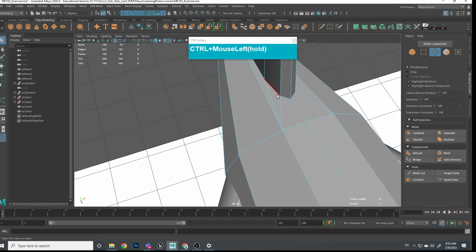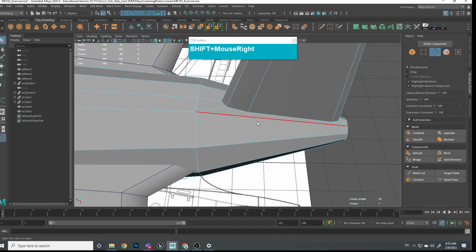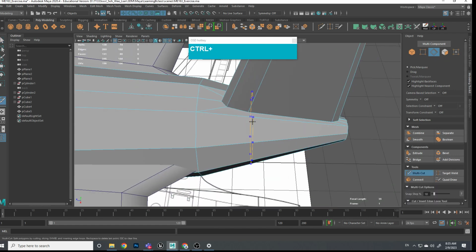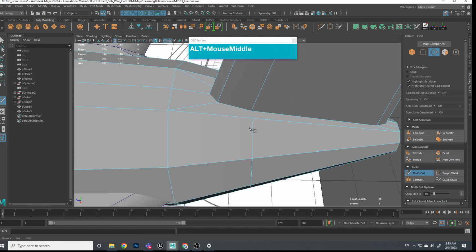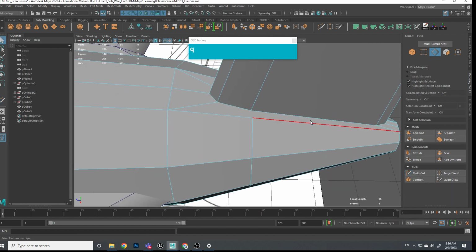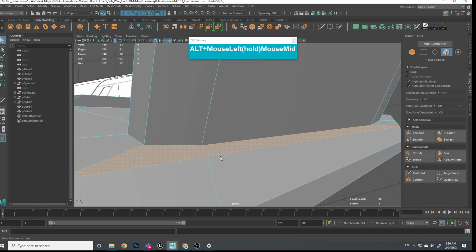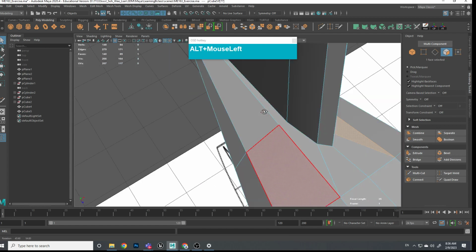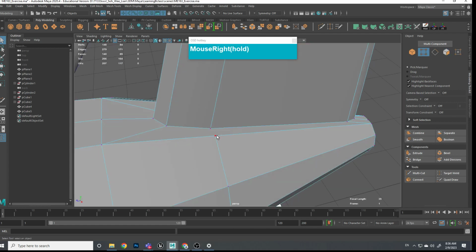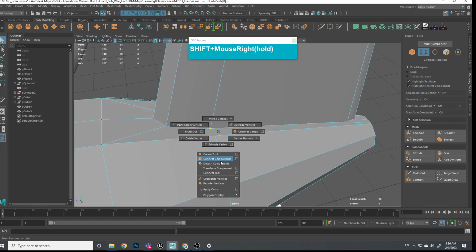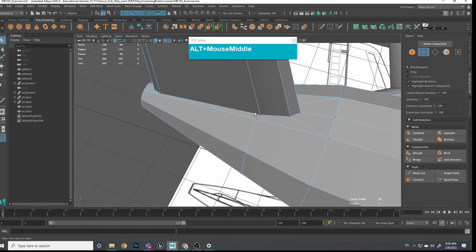Get rid of this one first, because the edge is too extreme. So I'll insert one edge loop here. Okay, so you can see that there's a multi-sided face over here. This multi-sided face over here. So the edge loop didn't cut over. But the rationale for me to insert one edge loop here is so that I can join these two vertices. And I think the connect should work now. Yes, it does. Select these two and then press G, repeat the connect.